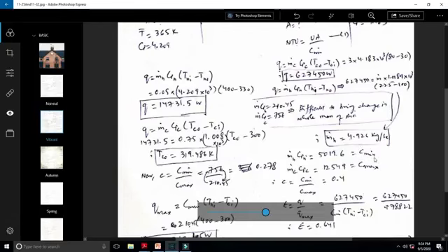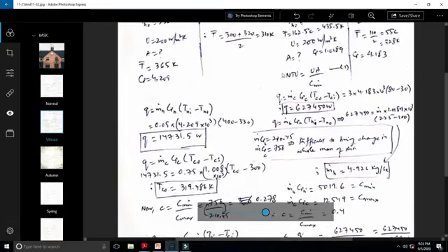This would be called Cmin, and this 12,000 is the greater one. Therefore, it would be called Cmax. Therefore, Cmin over Cmax, meaning 5019 over 12,549, will give us a value of 0.4. So out of the values in this expression, we have also found Cmin. The last thing is to find out NTU.